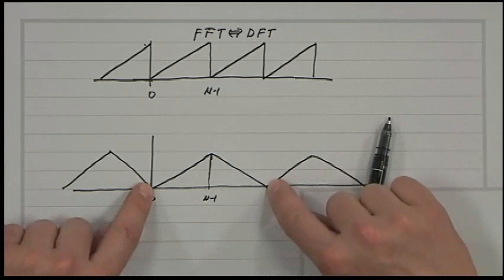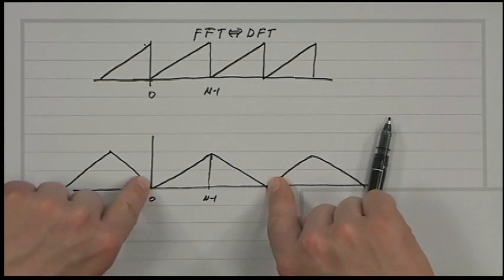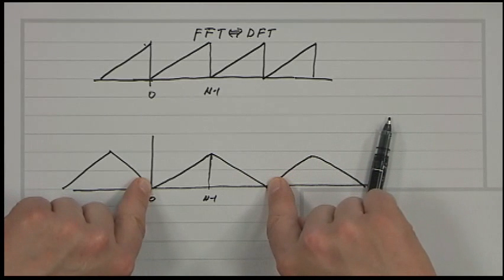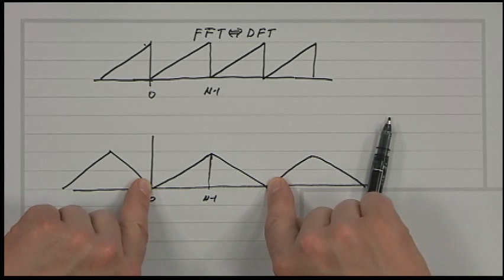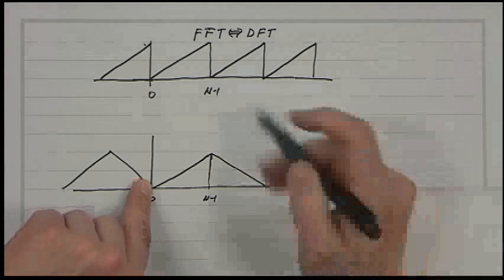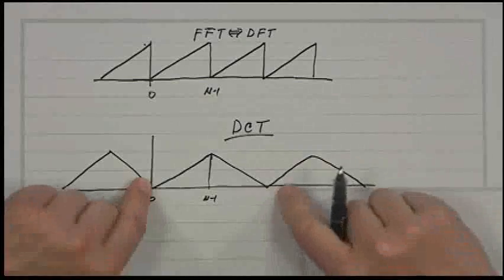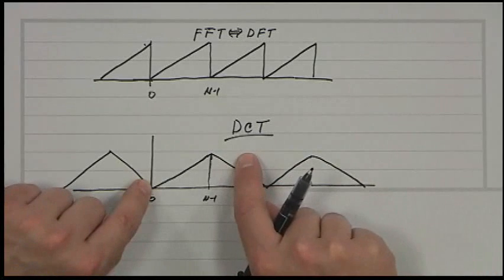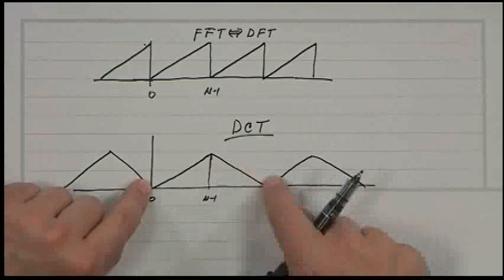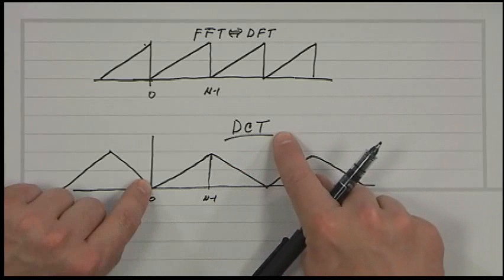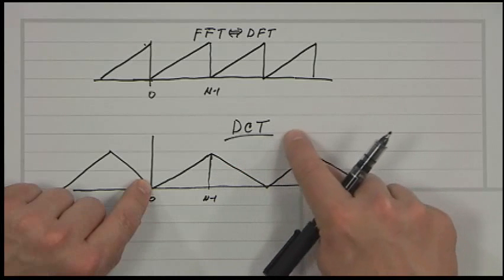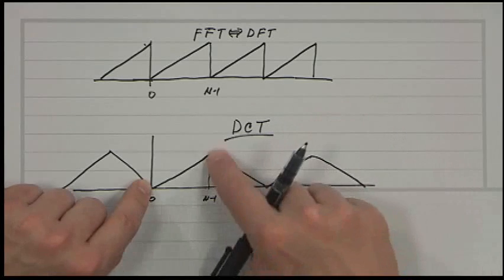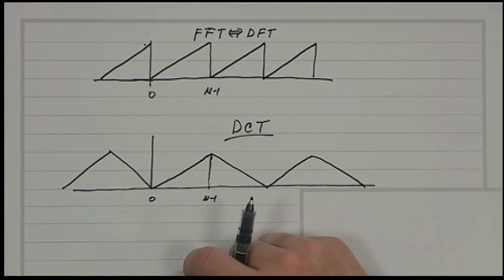When you take the FFT of this longer signal, which is now symmetric, what will happen is that you get twice as many coefficients, but now they're real valued because of the symmetry. So that becomes the DCT. So the DCT is basically assuming that the signal is reflected periodically instead of just repeated. So it's smoother, and you don't get high frequency noise basically splattered into the high frequencies because of sharp edges.